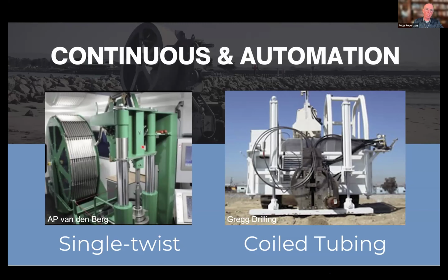Of course, if you're going to do seismic, you need to pause to measure shear wave velocity. And while you're measuring shear wave velocity, you do a dissipation test. So usually the rods are not that much of a problem. It's actually quite convenient to have this ability to stop and measure shear wave velocity. So when we first started measuring shear wave velocities, since the rods are 1 meter long, we would typically measure shear wave velocities every 1 meter. It was a very convenient thing to do. And of course, you're also collecting dissipation data every 1 meter.